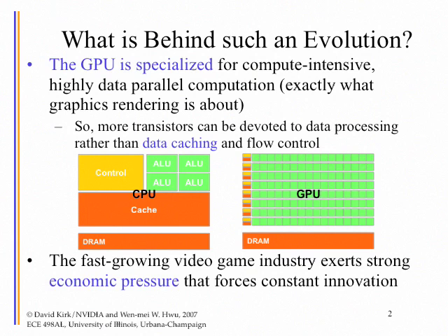Okay, this was the SIMD thing that I was talking about, right? So you have a huge number of these execution units, and now you have a little bit of a problem. The problem is because not a whole lot of data is sitting on the on-chip cache, you will have situations where you have to go out to the DRAM to get that data, right?